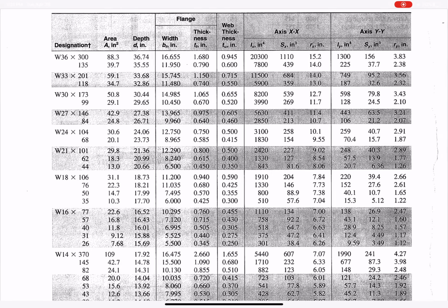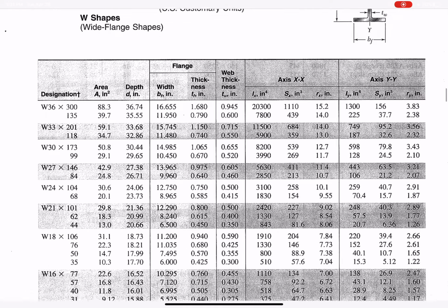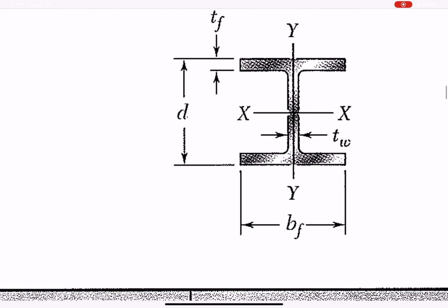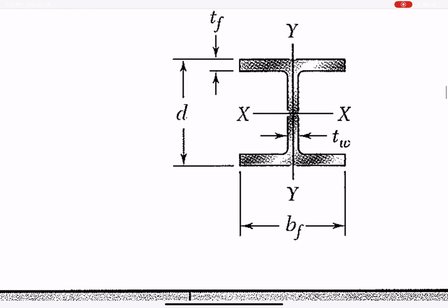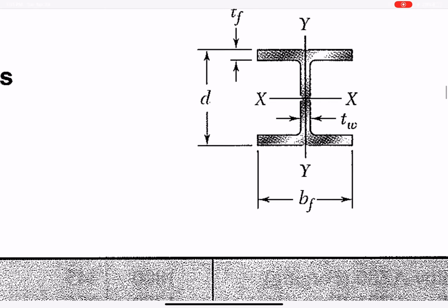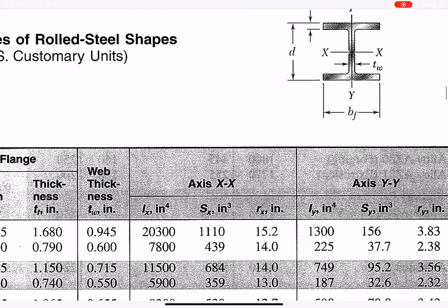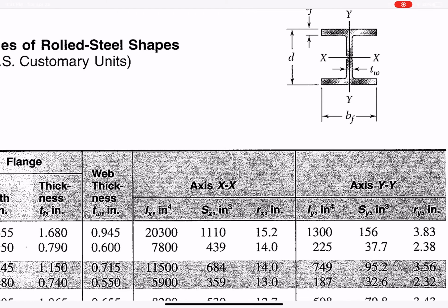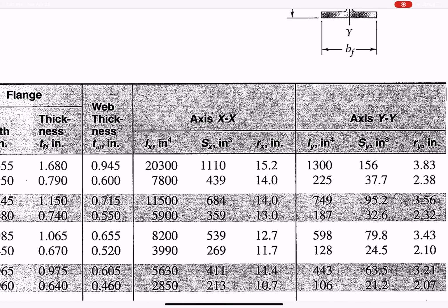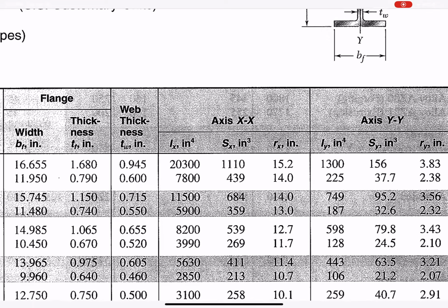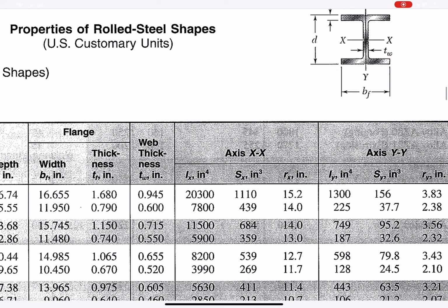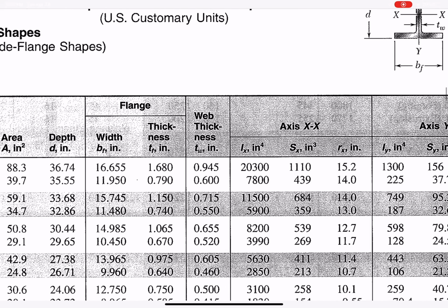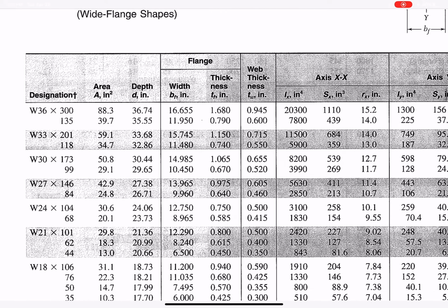We have SX, the section modulus for the X axis, because that is how the beam should be set up. That will give the maximum I to get the minimum flexural stress on that beam. So we will set up this way, not rotate the beam 90 degrees, which would give a smaller S in Y. So go to the SX.